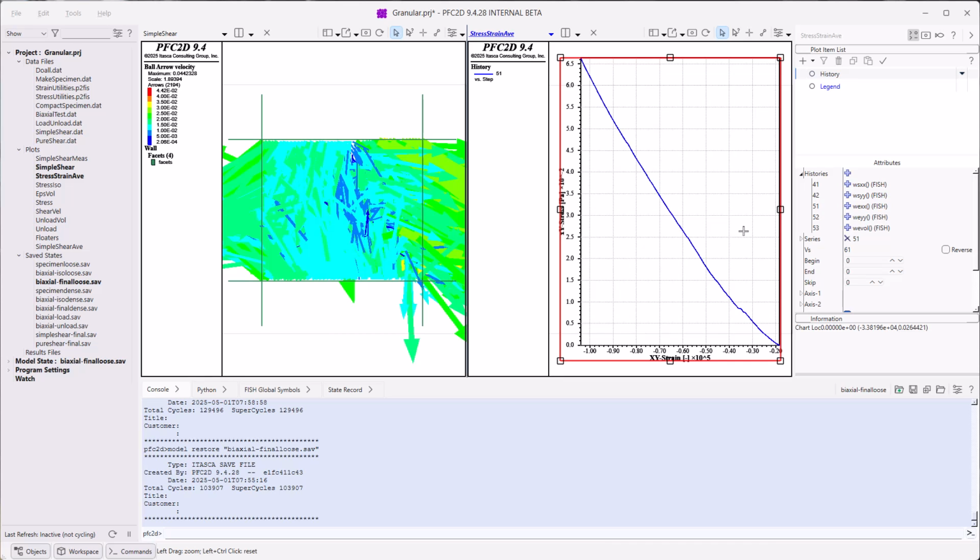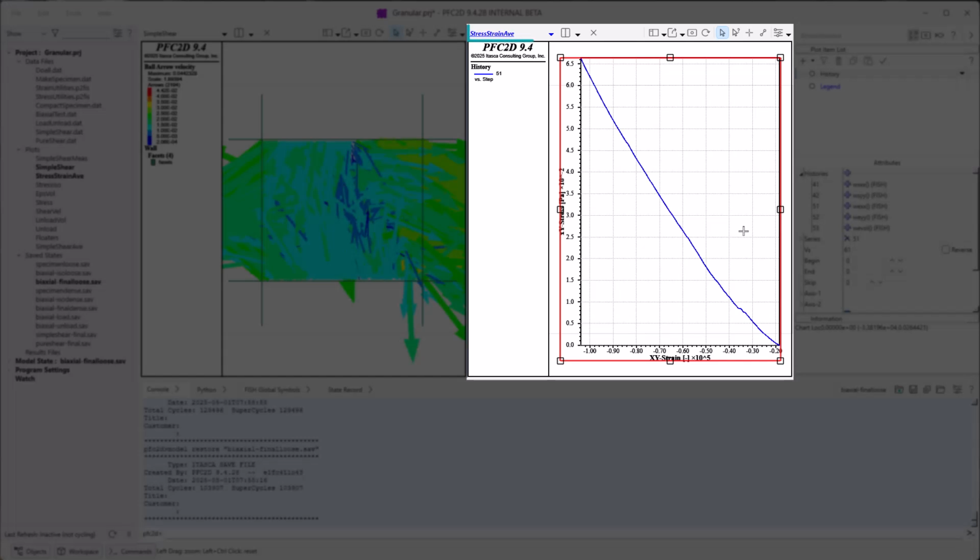So those are the 3 methods for opening items from the project branch of the Objects panel. As you can see, they each open items from the tree, but with trade-offs. The right-click method is clearest, probably, and the double-click method is fastest. However, with double-click, you have to remember which workspace window is active, because that is where a double-click command will occur.